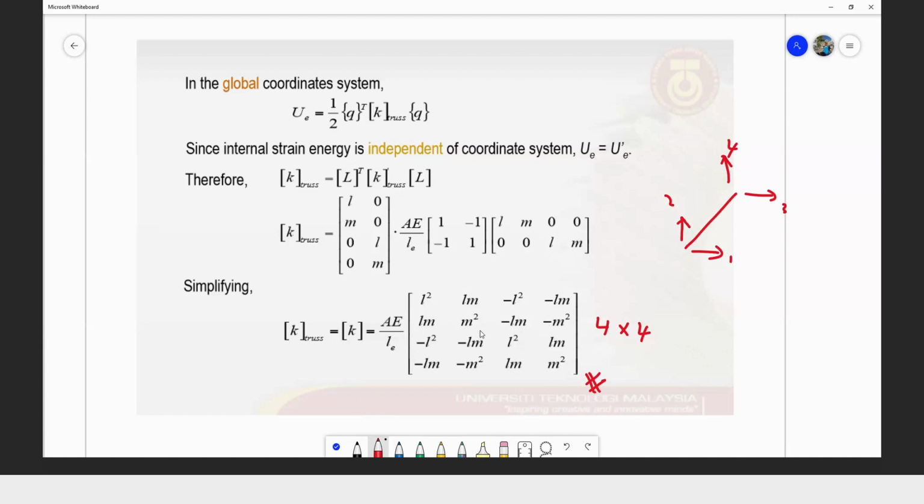And then what is contained in this K matrix, again it is the same. We have geometrical information of our truss element: A, and L, which is referred to as the length of our structure. The l and m refer to cos theta and sin theta, which are also still geometrical information of our structure. Only E refers to the material properties.